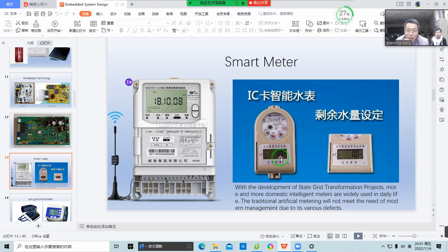Some just run in the main routine. It's different. If you make your time-related critical code run in the main routine, it's not good enough. You must place this time-limited code section in the interrupt routine.